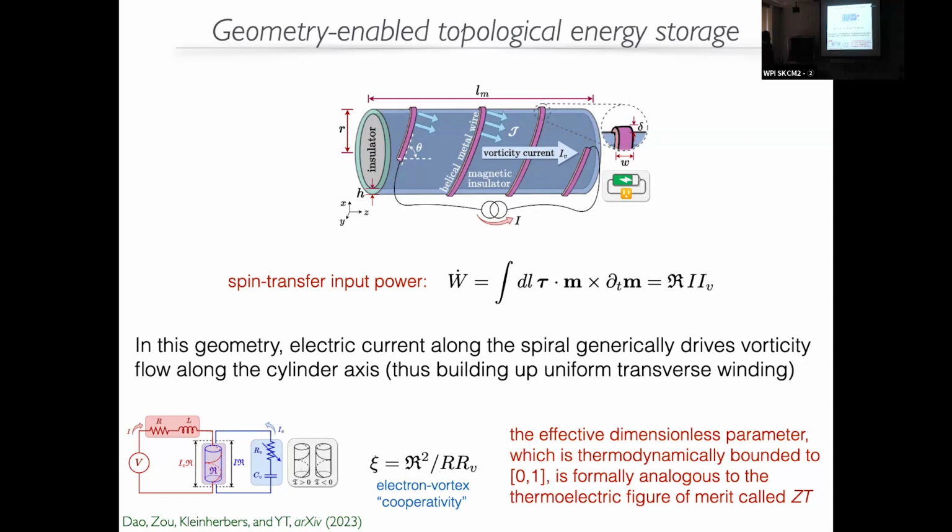And again, C sub V is going to be the analog of capacitance that corresponds to the energy stored in the winding configuration as a result of vortices moving across the system. Okay, that capacitance will be inversely proportional to the exchange energy. So that's my effective circuit for the vortex dynamics. That's already there even in the presence of this helical wire.